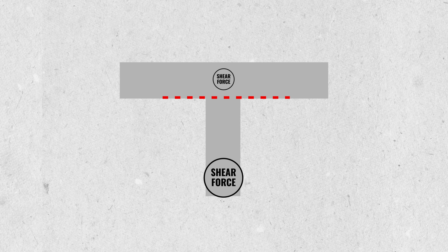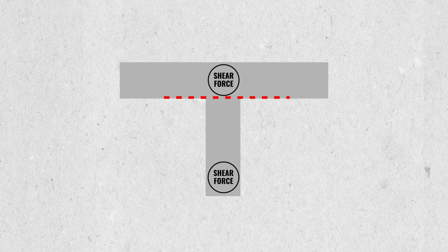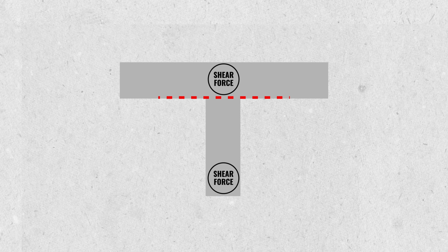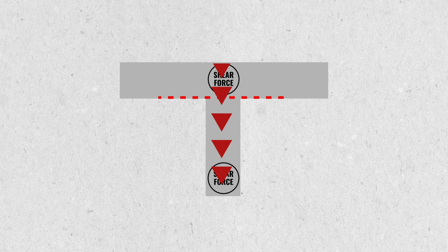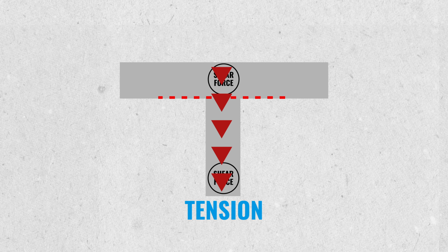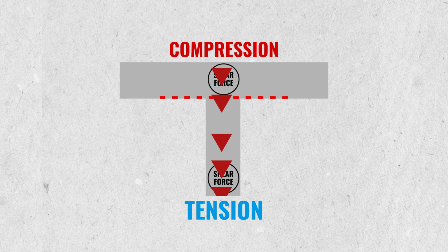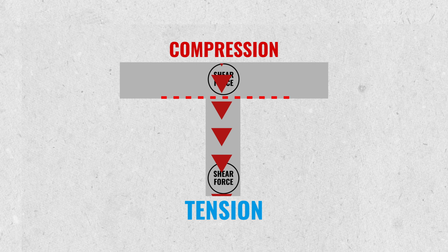And likewise, you need to change that shear force to make sure that shear force is transferring from that point to the points of support. So it becomes a strut and tie action where the force goes down, causing the bottom action to be in tension, the top action to be in compression, but then you also have these diagonal forces to finish off that strut and tie action to transfer those vertical forces through. So that means there's corresponding diagonal struts going backwards and forwards to the supports to change that action.